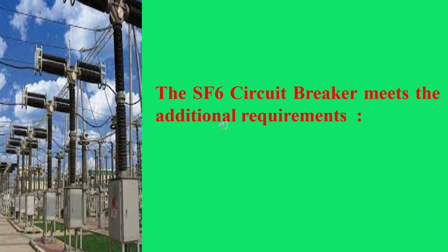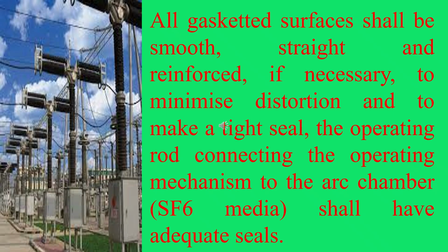The SF6 gas circuit breaker meets the additional requirements. All the gasketed surfaces shall be smooth, straight, and reinforced, if necessary, to minimize distortion and to make a tight seal. The operating rod connecting the operating mechanism to the arc chamber shall have adequate seals.